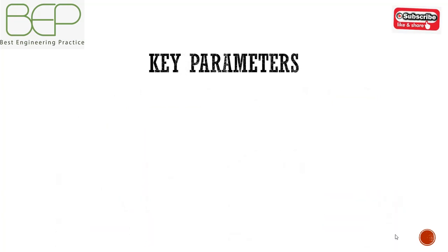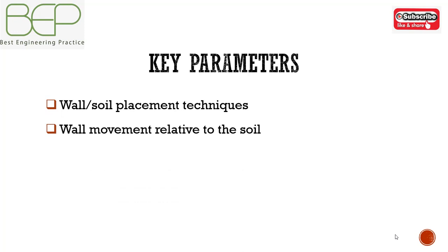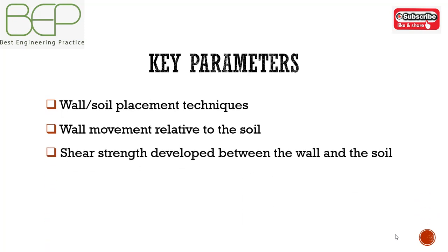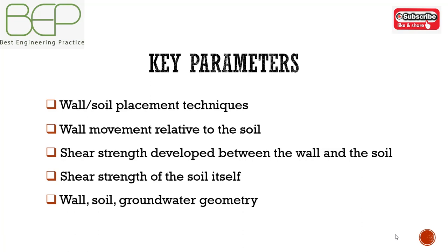The magnitude of earth pressure mobilized on the structure will be related to wall and soil placement techniques, wall movement relative to the soil, shear strength developed between the wall and the soil, shear strength of the soil itself, wall, soil, groundwater geometry, and external loads.